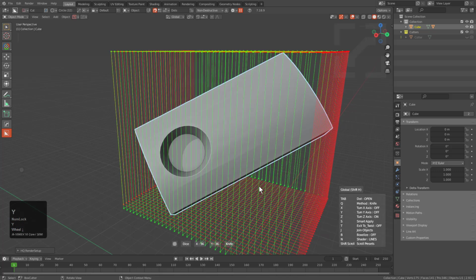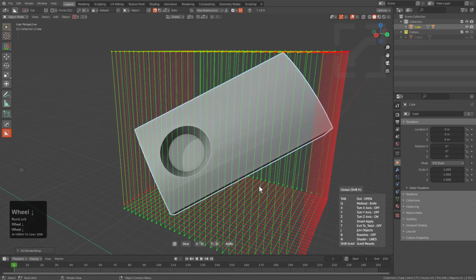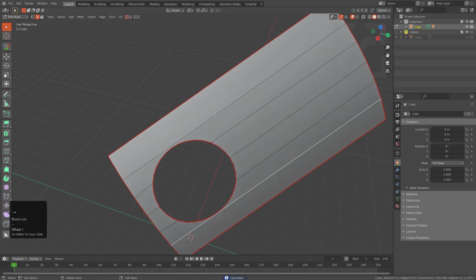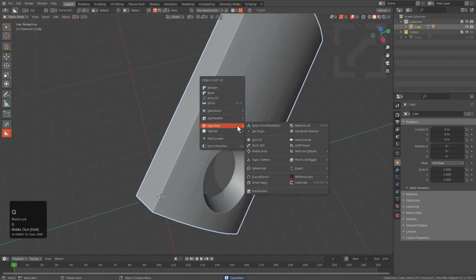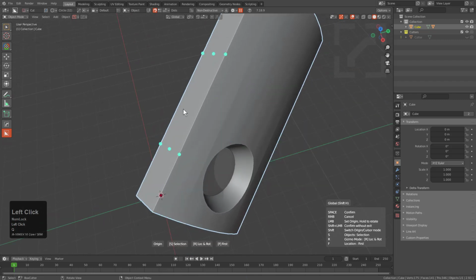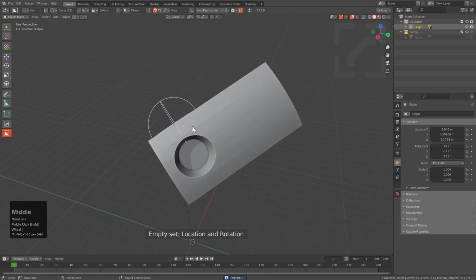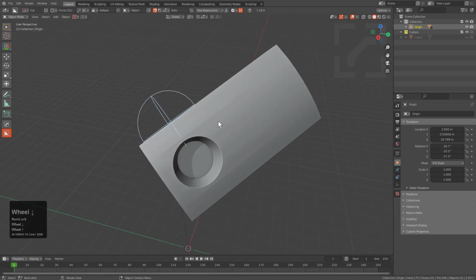So we see that just normal dice isn't going to cut it for us. And this is one of those cases where an empty override would actually be needed for the surface. So using set origin, we now have the ability to press A to change the cursor mode, which has always been a thing. I just haven't talked about it yet. A again will change you over to empty mode, where basically we can drag from dot to dot, and we've basically created an empty that's actually oriented to this particular area that we've drawn the empty on.